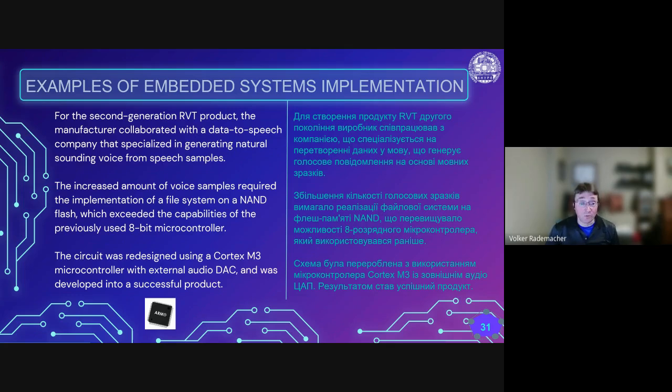If you read the same location in a NAND flash like 100,000 times, which was part of the testing procedure, basically to read the same voice sample many, many times continuously for a month, some of the NAND flashes can basically lose the data. It is not technically a bad block because it can be rewritten, the block is still okay, but the data is lost.